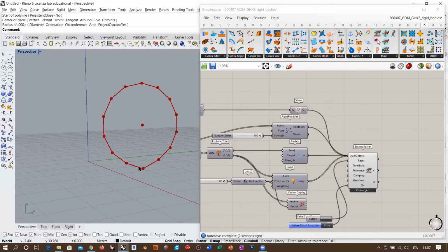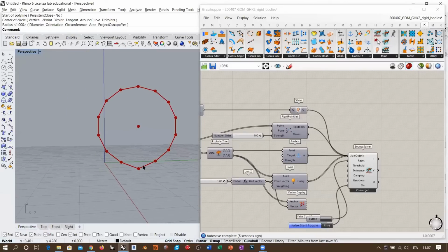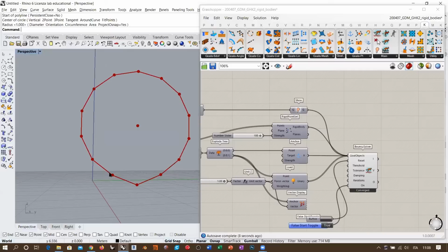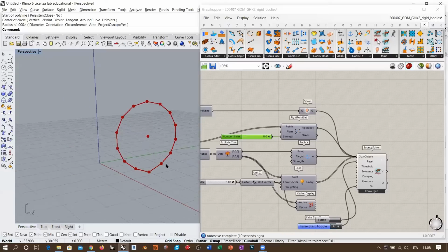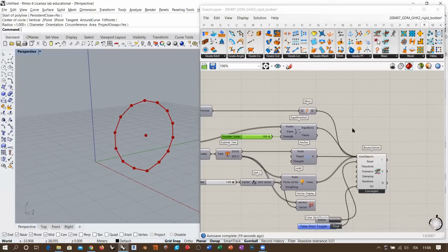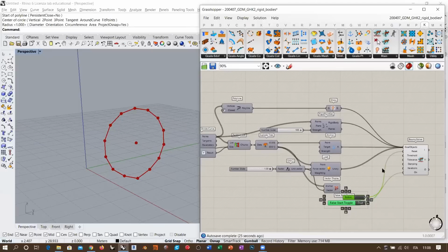You see that there is still some stretching, which was hard to see while working only with particles or points. So it means that we can also increase the strength of the rigid point set a little more if we want to get rid of this slight deformation, okay? But anyway, this is something that you can adjust accordingly. It's very easy at this point. So yeah, basically that's it for the rigid set of points.